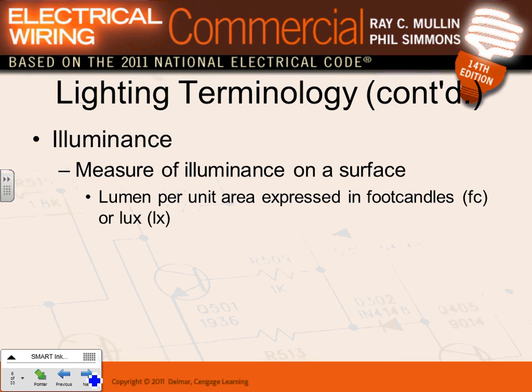Illuminance is defined as the measure of illumination of a surface. So you take your lumens, like we said, divide them by the area, like we have done many times, and that will give me my foot candle. This is the simplest form of it. Take lumens divided by area, you've got your foot candle. Of course, there are other factors, like we did yesterday. It's not as simple as this.